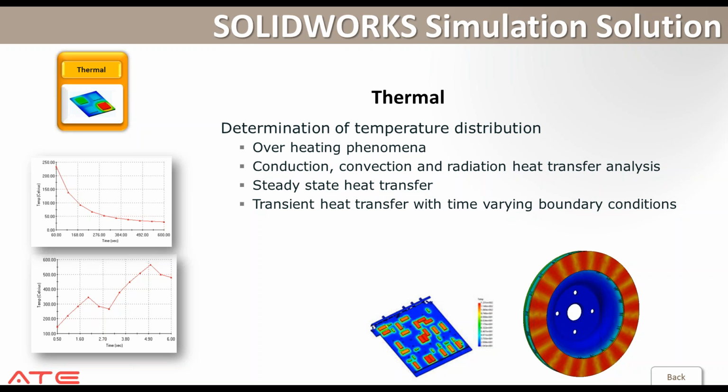So additionally, after you have calculated the thermal analysis, after you calculated the thermal value or the temperatures at the end of the steady state, the data can be transferred back into static analysis or any nonlinear analysis for further residual stress calculations or thermal expansion calculations that cause warping phenomena or scenarios. So this is where the thermal analysis comes in, especially useful in the semiconductor industries, where warpage is one of the factors of failures in the analysis.